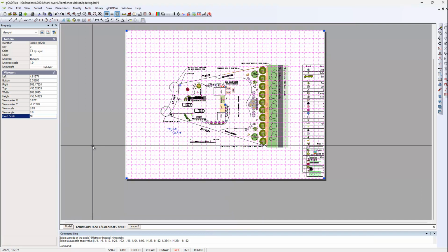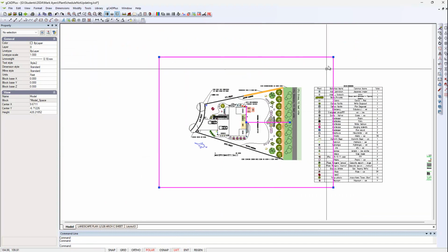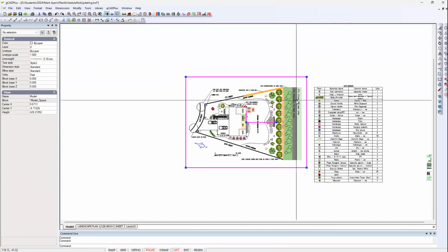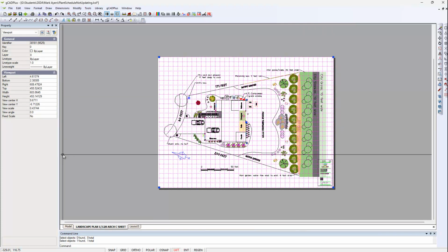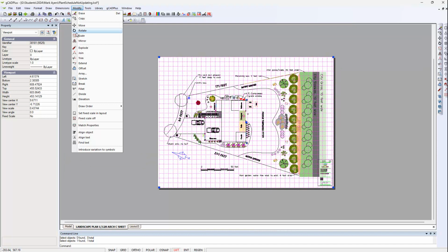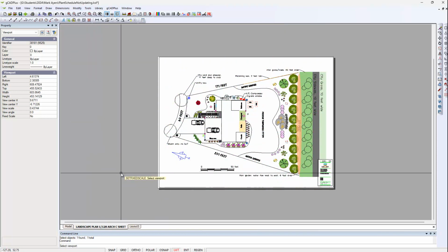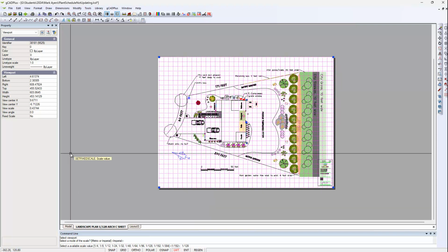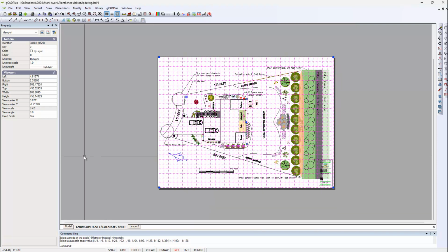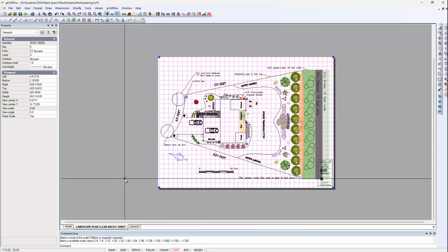If you take off that and dive back in, you can then change what you see on the layout, like so. And to reset it how I had it, it would just be the same. Modify, set fixed scale, pick, follow the prompts, pick the floating viewport, and we want 1 over 128, and you'll notice that when we do that, it automatically locks this setting in the properties box to a fixed scale.